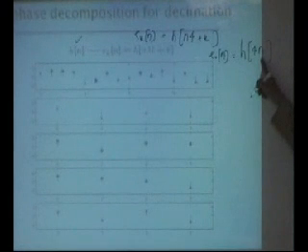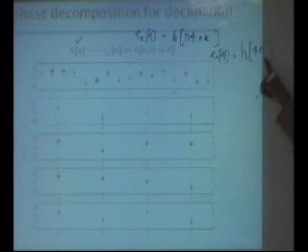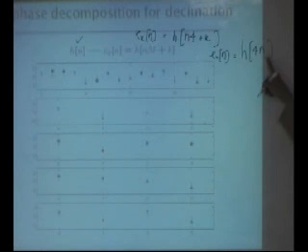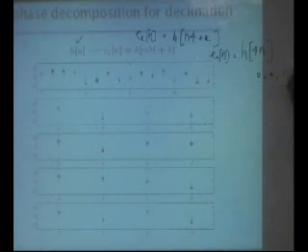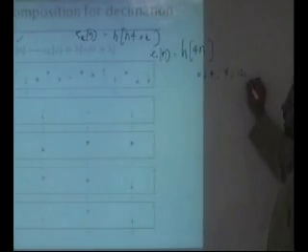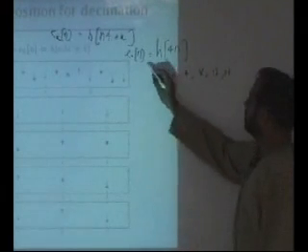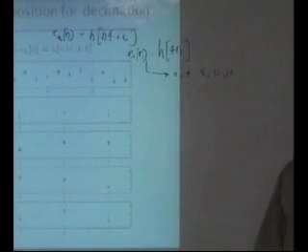The first sample is h of 0. Then put n equal to 1, the second sample is h of 4. The third sample is h of 8. So the first filter will get the 0th sample, the 4th sample, the 8th sample, the 12th sample, the 16th sample. This is your E0 of n.